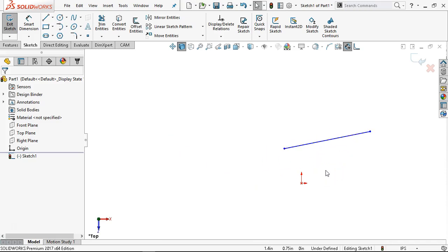Those parameters will put you into position. If you know that position and you need that position, fine, use it. But if you do this on every one of your objects, you're going to make this program miserable. It is going to be a royal pain because we are freeform sketch, parametric. The relations and the dimensions drive the geometry, our objects. Those relations, those dimensions are the driving force.